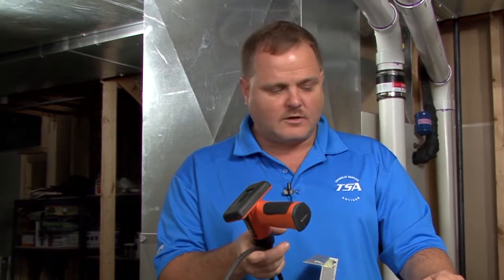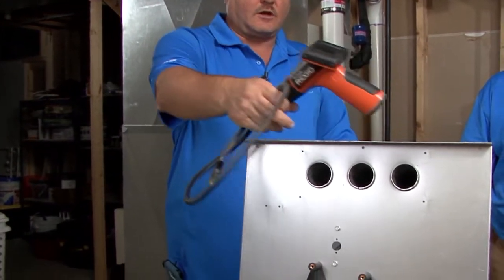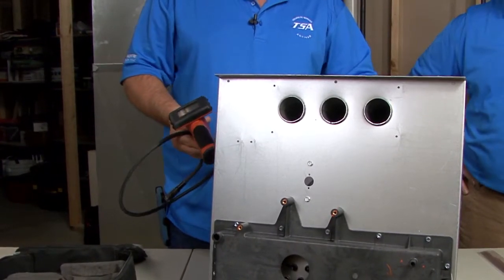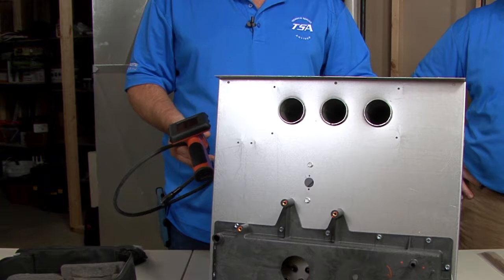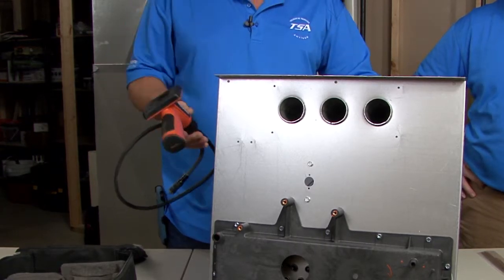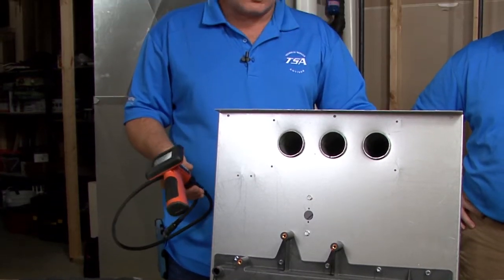Absolutely, Dana. So I got a camera here. We're going to talk about that a little bit. I'm going to turn this heat exchanger around and give you the synopsis of what some guys will do with a snake camera. And I have to agree with you completely, Dana, that using a snake camera is not really the best tool to be looking for a breach in the heat exchanger. Although they have a lot of useful purposes, and I've used them out in the field myself and had great success with using them. One of the things I used them for all the time was to pull the blower back a little bit and look up in there to see if the secondary heat exchanger coil was dirty.